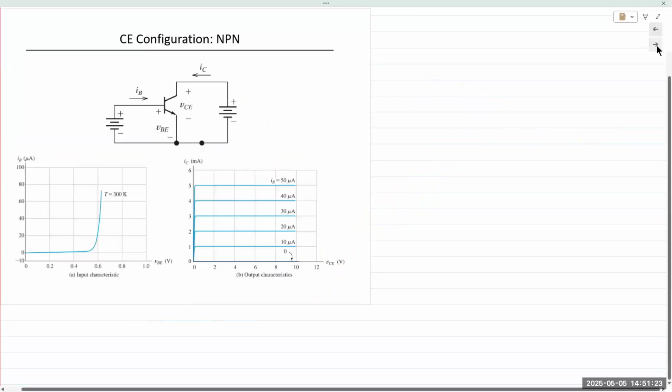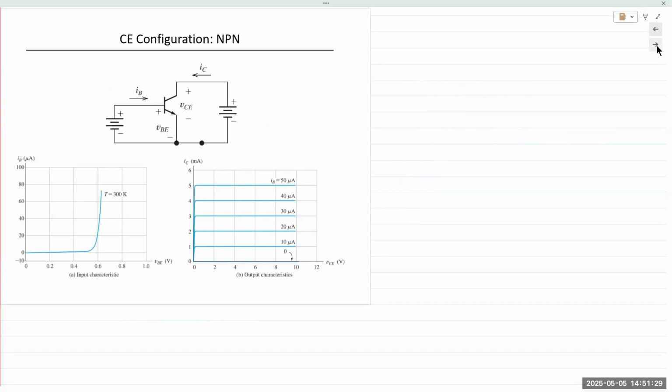Again, you're not going to end up blowing out the transistor. You're simply forward biasing the collector and base, but the collector does not have any free charge carriers. Very limited. It's almost close to an intrinsic semiconductor. It would not have much charge carriers available, so you could apply a very high electric field and it still wouldn't work.